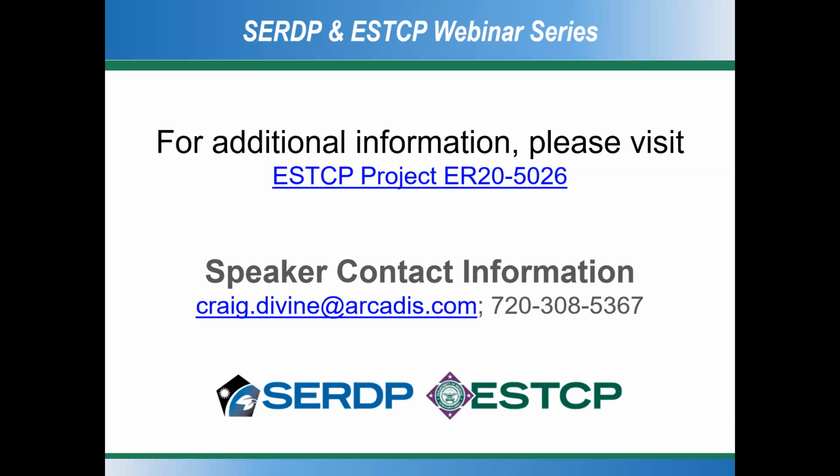This next one is from the Michigan Department of Military and Veterans Affairs. Do you think the drilling mud coated the well screen and impacted the observed hydraulic conductivity that you reported? Yeah, that's a great question. Just in general, mud-based drilling offers that challenge. In this particular case, we used a biopolymer mud that is biodegradable, and we used an enzyme breaker to facilitate that degradation.